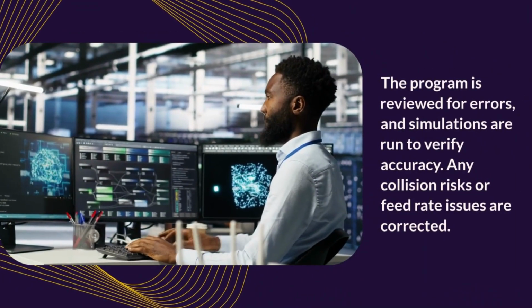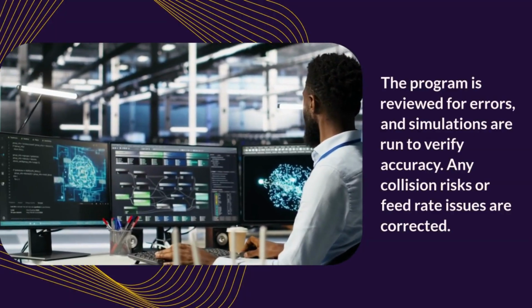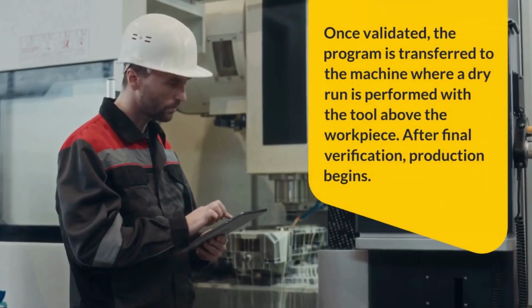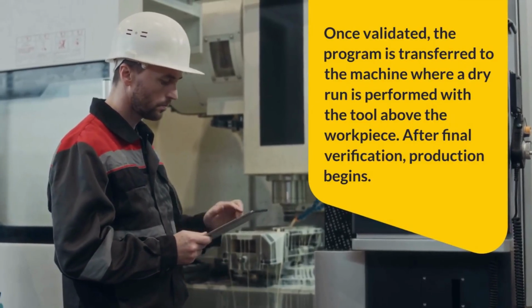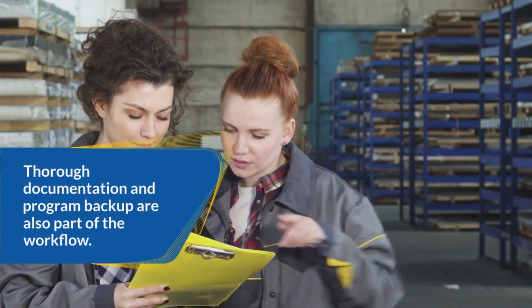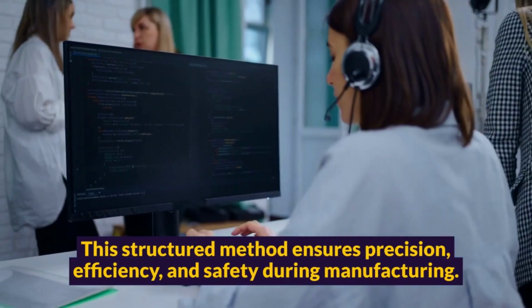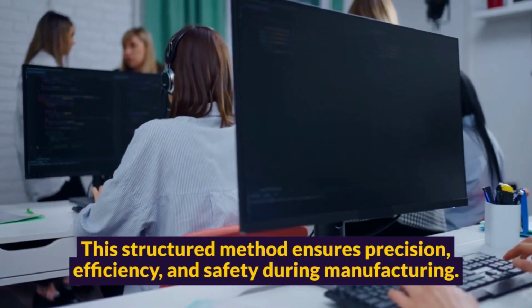The program is reviewed for errors, and simulations are run to verify accuracy. Any collision risks or feed rate issues are corrected. Once validated, the program is transferred to the machine where a dry run is performed with the tool above the workpiece. After final verification, production begins. Thorough documentation and program backup are also part of the workflow. This structured method ensures precision, efficiency, and safety during manufacturing.